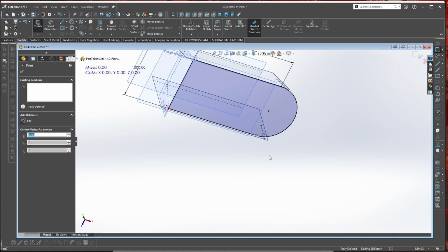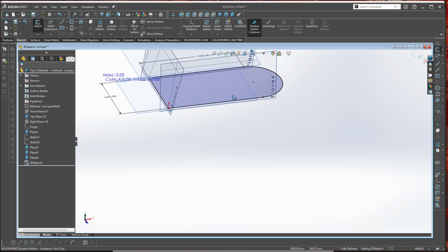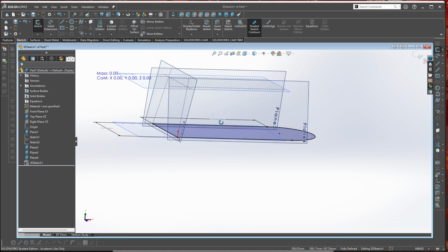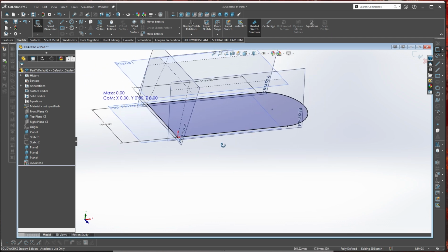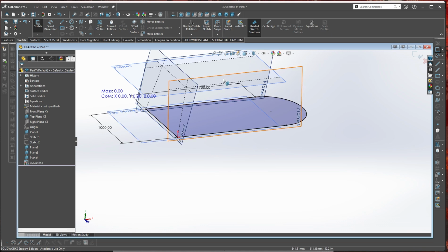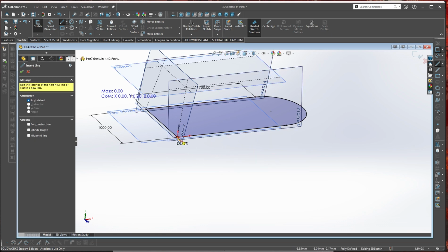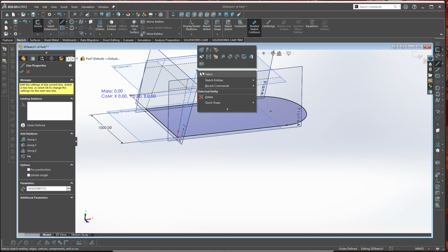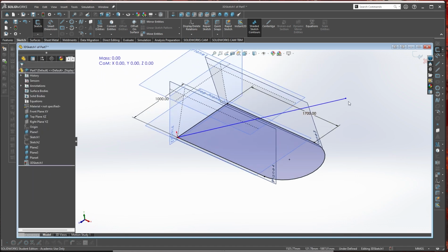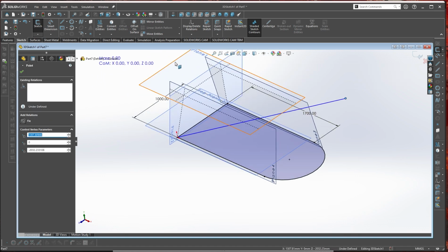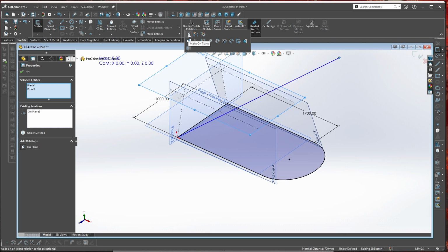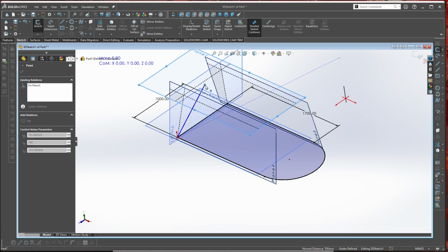So I can't move anything more, and now I can keep going with the sketch. So unlike before, instead of just having a point to point, notice we're going to draw a line from here up to this plane and lock this into that plane, that end point. We're going to do that and then some more. So let's go ahead and start in on our origin. Somewhere over here. It's not even close, but what we're going to do is close this, and we're going to create our make on plane relationship like we did last time.